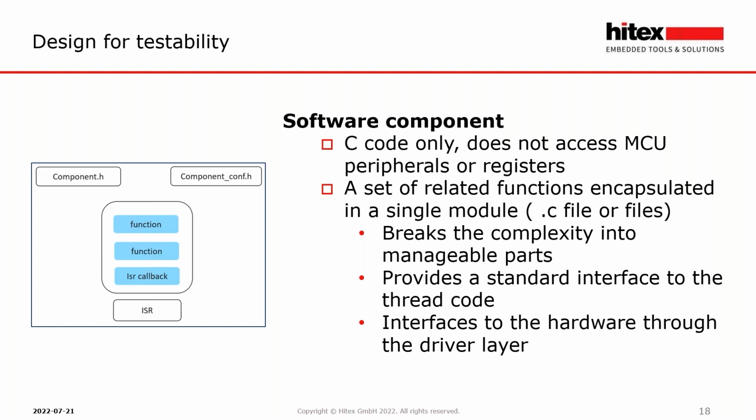And ideally, it's also very much isolated from the underlying microcontroller hardware. So we should create a driver layer that is the only software that actually talks to the hardware. And then the bulk of our code is pure C code that really is making calls into the driver layer. So by structuring our C code, we make it much easier to test.